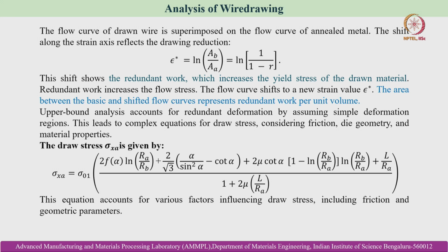This is also the reason, please recall that earlier we discussed, when we were discussing offset forging, about keeping this flash. That flash also facilitates complete filling of the die cavity by the workpiece material to achieve the desired shape of the component made.